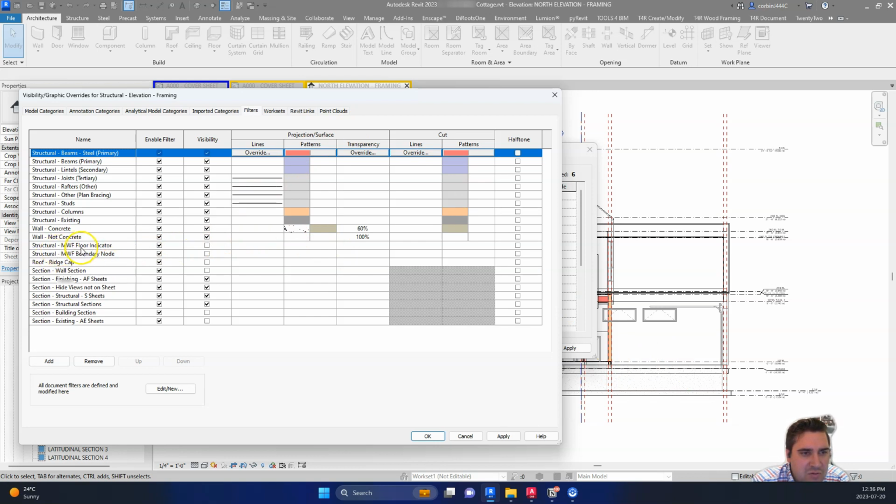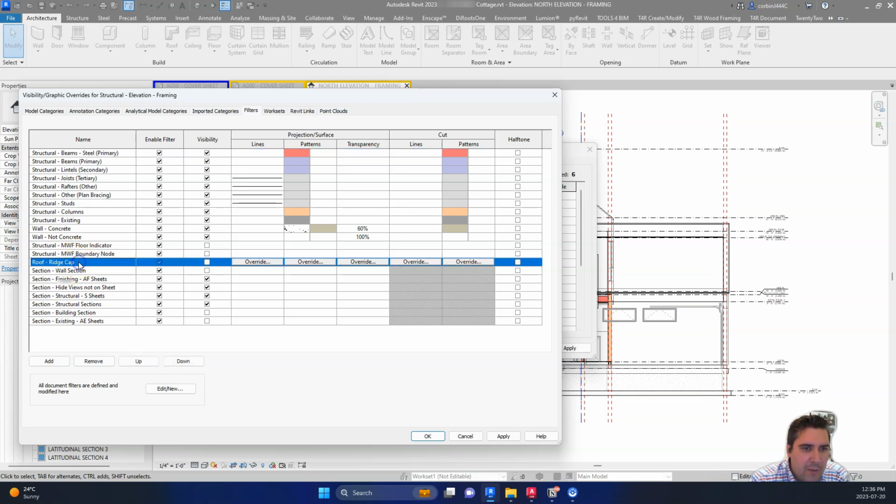We have a plugin we used to use, called MWF. We actually don't use it that much anymore, and so we turn off a lot of those functionality pieces and indicators. We have a ridge cap, and so we search by a specific type to turn off that ridge cap. We hide our wall sections because we don't show our wall sections in our elevation views. We only show those in floor plans, and we have different types of sections based on what we're doing. So we have those filters set up to do that. So that's a bit of an overview.